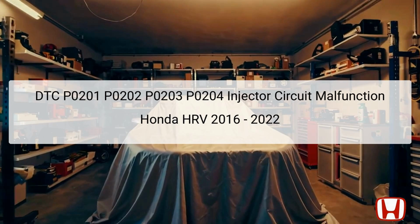This presentation focuses on diagnostic trouble codes, DTCs, P0201, P0202, P0203, and P0204, relevant to the Honda HRV from 2016 to 2022. These codes indicate malfunctions within the fuel injector circuits for the respective cylinders. Specifically, P0201 refers to the number 1 cylinder, P0202 to the number 2 cylinder, P0203 to the number 3 cylinder, and P0204 to the number 4 cylinder.